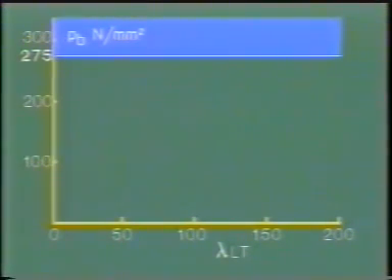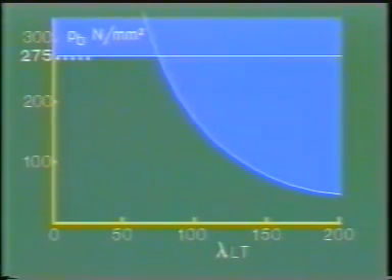Conversely, whatever the material yield strength, the beam can still fail by lateral torsional instability. In terms of extreme fiber stress, this behavior plots as a line which has a very low value when the slenderness is high, but has a very high value when the slenderness is low. This line, too, is an upper bound to the actual bending strength. For low slenderness material, strength is the limiting condition.